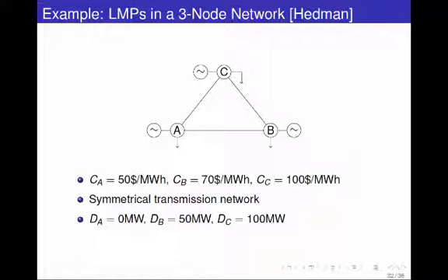One way to deal with that, and it turns out it's the cheapest way, is to have an equal amount of power produced by this generator and back this one down by 2 units to make up for the increase of this one and the increase of this one minus the 2. So they're going to both ship power to B, but this generator's flow is going to cancel this one's flow, so the line will remain intact.